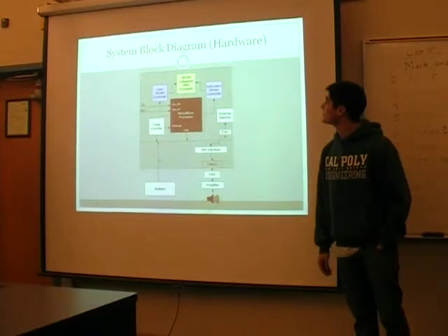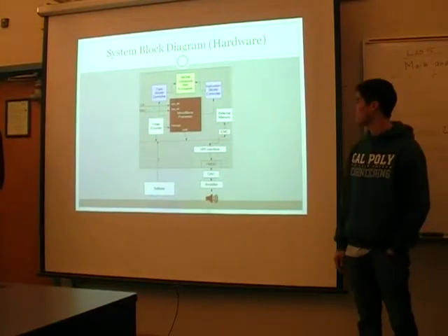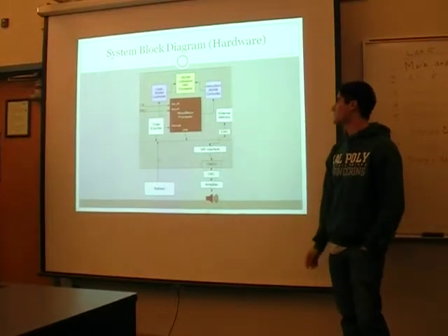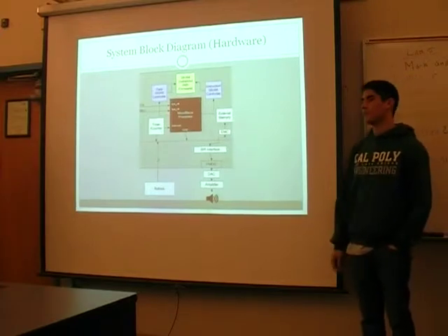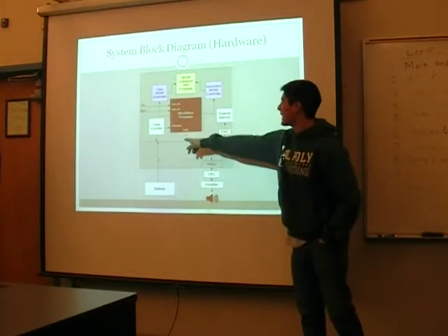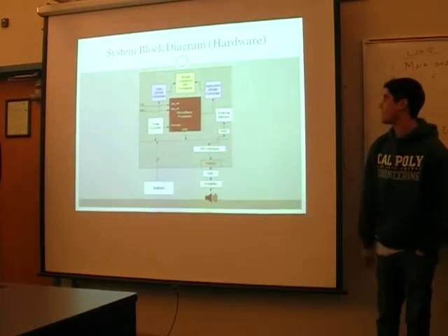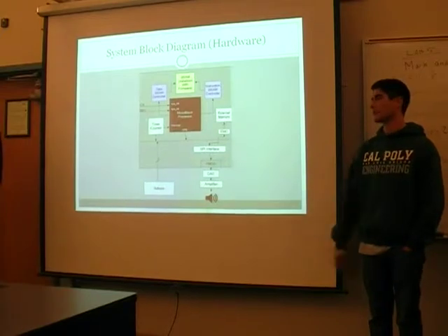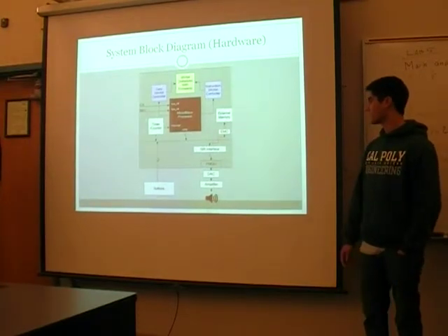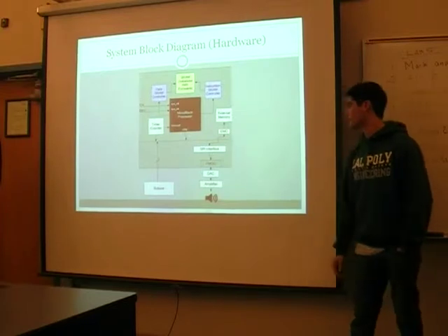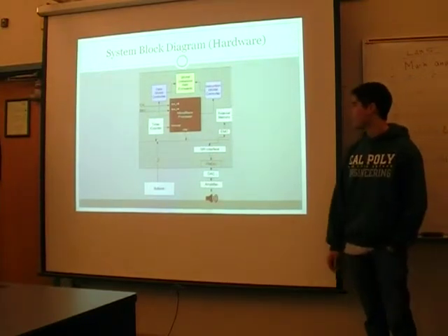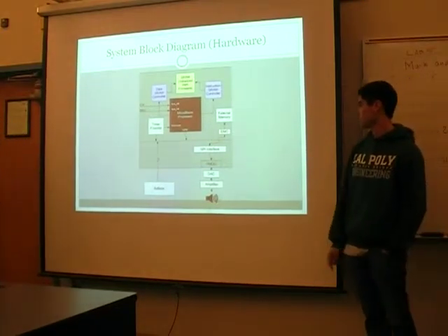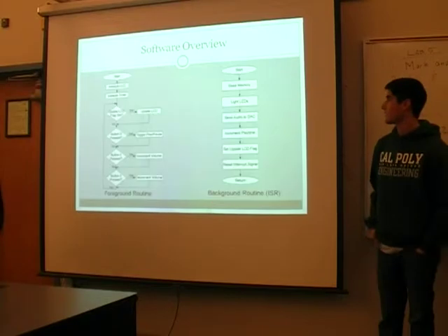And here's a block diagram of the hardware. Basically, for our external memory, we had to make sure that whatever song or wave audio file we put in there, the timer and counter were set to the correct frequency for that wave file, so the interrupts were correct and it wouldn't go too fast or too slow for the song. We also used the DAC, a digital analog converter that we purchased from Digilent, and the speaker headphone amplifier, the other PMOD we used.